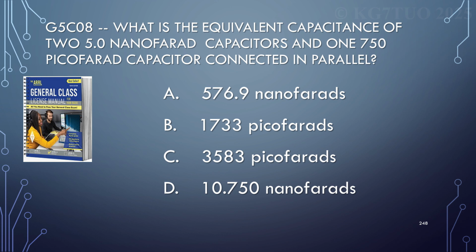These questions take forever to get through if we let them do the math, don't we? Yeah. Just memorize it. Well, not really. In capacitors in parallel, just add up the values. It's additive in parallel. The only tricky part about this one is nano and pico.